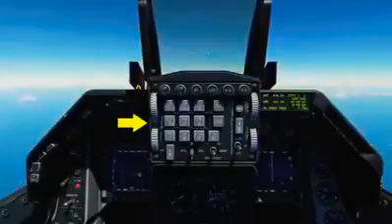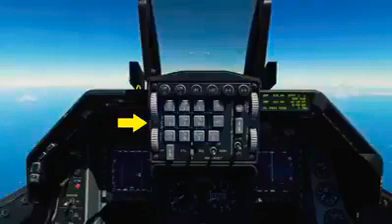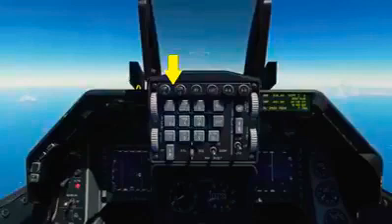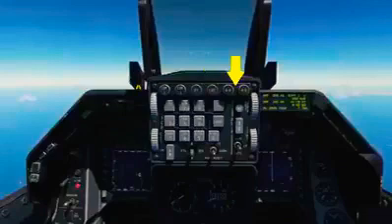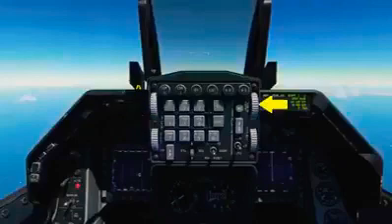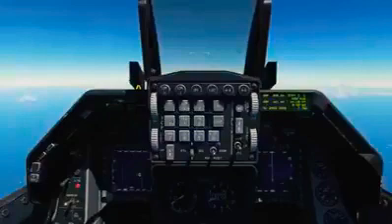The Integrated Control Panel, or ICP, fills the top portion of the center instrument panel and is one of the core systems of the Communications, Navigations, and IFF, or CNI, in the Viper. We'll talk about specific functions in later videos, but an overview of the functions include the following. Radio 1 and 2 control buttons, the Identify Friend or Foe button, the list option that displays options on the Data Entry Display, or DED, select either air-to-air or air-to-ground master modes, wheels to control brightness, symbology brightness, reticle depression, and raster contrast. The raster selection is not applicable to this F16 version.